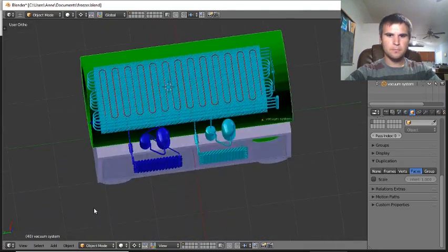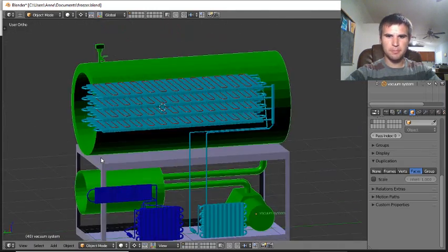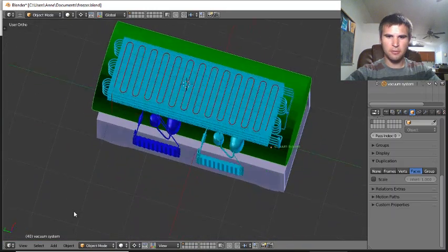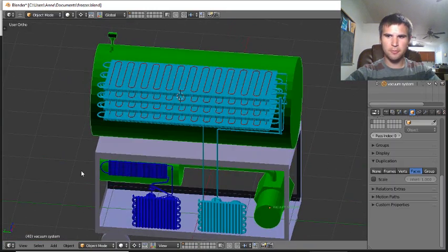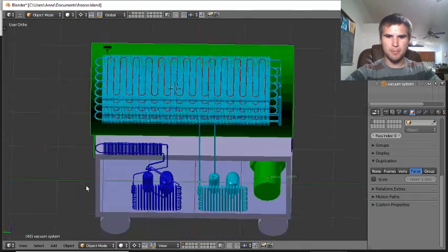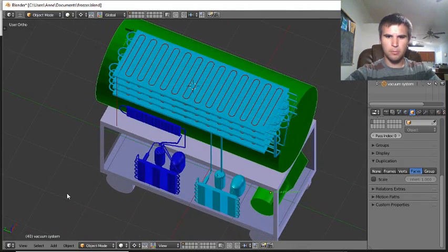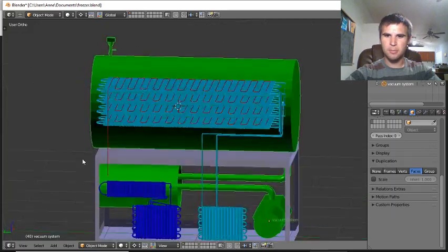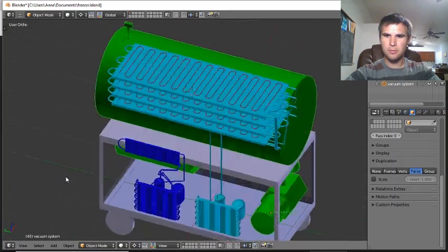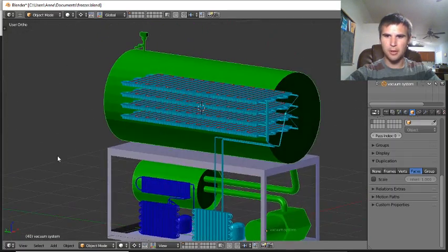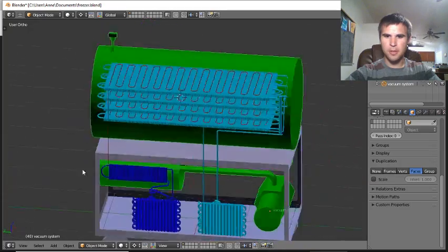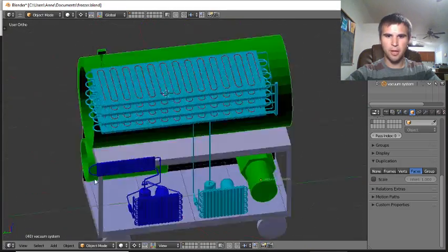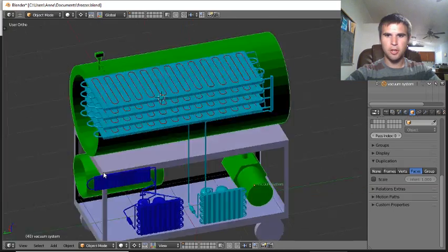I followed your advice, I think, just for simplicity and reliability, to not have the product refrigerator be a heat pump. Because we're going to be running it for such long periods of time, and because it's the bigger and more important of the two, I think just having it be a fixed metering device refrigeration system that we rob out of some kind of a freezer and put in there.